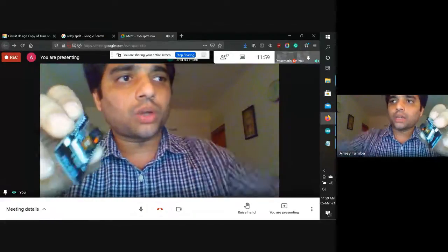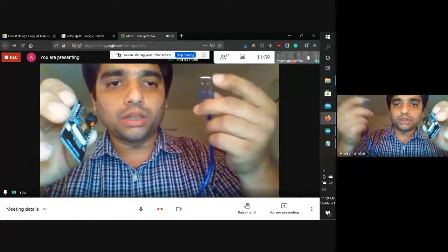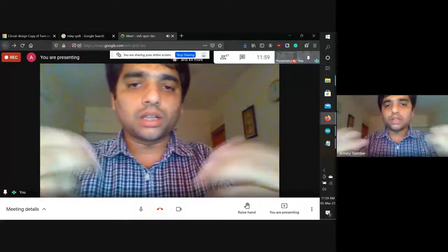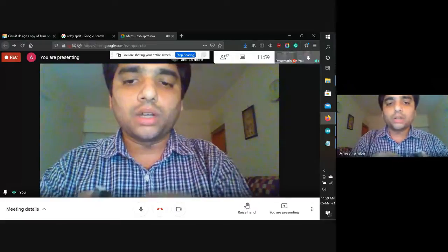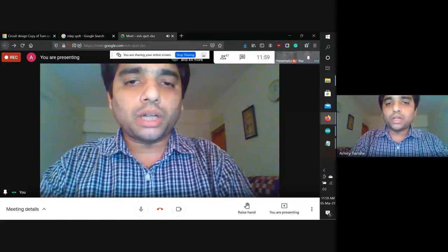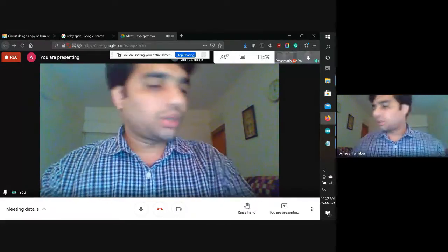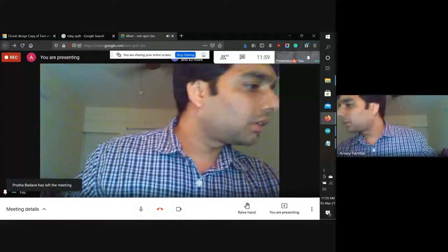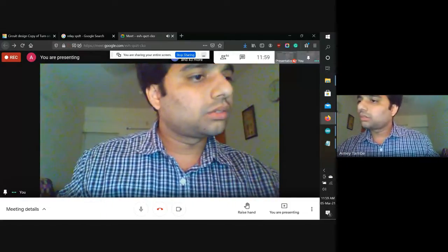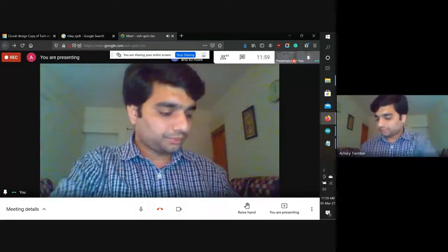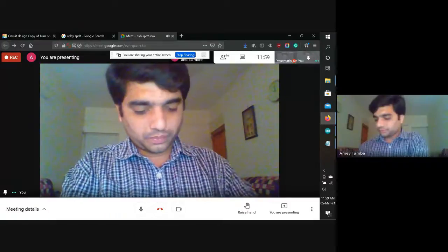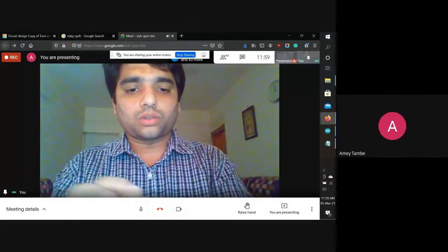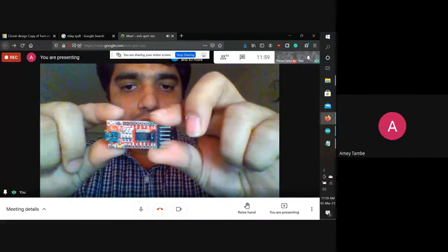Right? So let's see how to program this. If you notice, there is no input section, so we cannot connect it with a cable. For this we'll require an external USB to TTL converter. TTL is what? The pin outs. So a USB to TTL or UART converter. Here I am having it. Okay, so this is the USB to TTL converter.